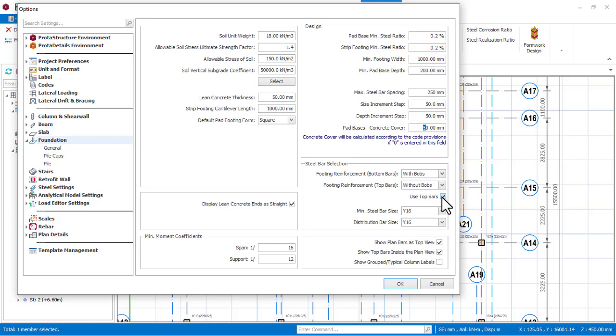Then you can now choose to use a doubly reinforced, which is the top and bottom reinforcement. Apart from that, it is good to use just the bottom reinforcement and not the top reinforcement. Now, another case where you have to use a doubly reinforced is when you are designing for a combined footing. When you're combining two columns on one footing, then you have to use that design for the combined footing for doubly reinforced for every combined footing.